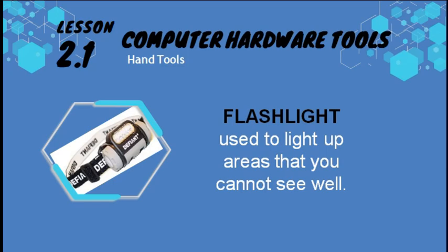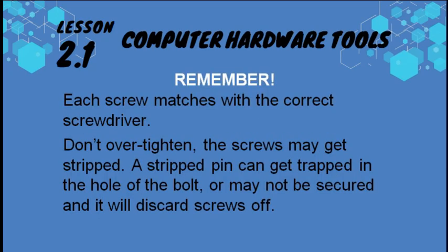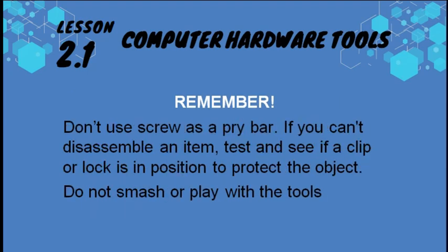Flashlight, used to light up areas that you cannot see well. Remember, each screw matches with the correct screwdriver. Don't over-tighten. The screws may get stripped. A stripped screw can get trapped in the hole of the bolt, or may not be secured, and it will discard screws off. Don't use a screwdriver as a pry bar. If you can't disassemble an item, check and see if a clip or lock is in position to protect the object. Do not smash or play with the tools.